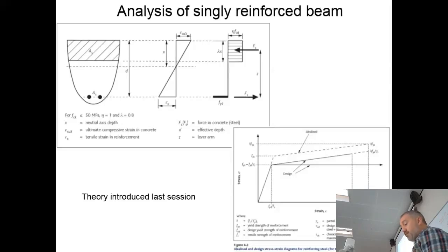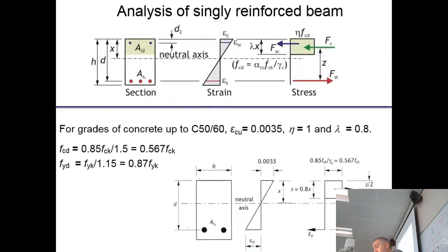So in the Eurocode on page 36, we have our stress block and stress-strain diagram, and I believe I've put in your notes this page, which is the same thing, except it shows you more clearly the factors of safety that you apply to each of the elements. That's above the blue line. Below the blue line is each of those with the UK national annex.